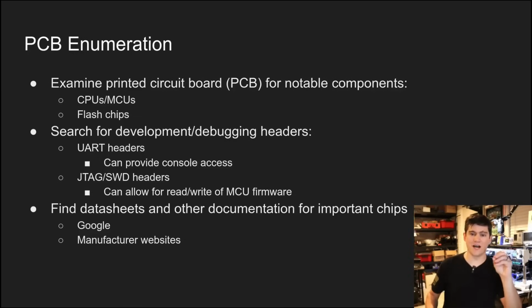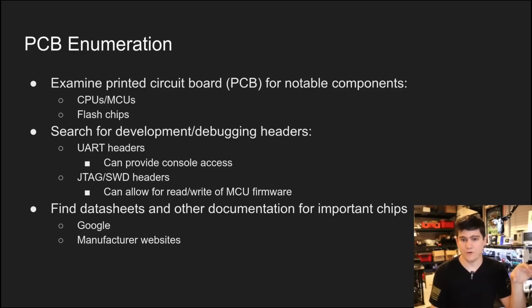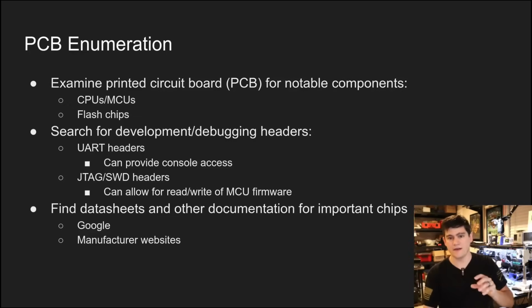We are going to talk about firmware extraction completely and do a deep dive of that in the next video. So I'm not going to talk too much about that right now. But then we're also looking for different debug headers. And so we have UART, which is a common interface that we are looking for that allows us to interface with a device's serial console, potentially. And we're going to see that.